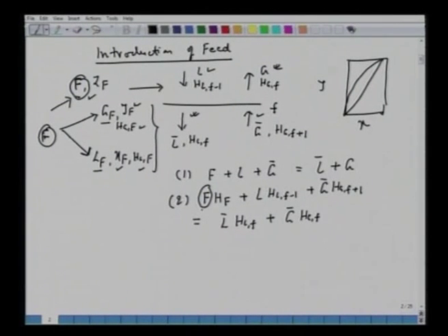Let's just work on this total molar flow rates of the feed as F, and this has a total enthalpy, specific enthalpy as HF, which can also be written in terms of HGF and HLF, etc. Now we make one assumption here that since the temperature drop across two consecutive trays is not very significant, one can assume that a specific enthalpy HLF minus 1, the specific enthalpy of the liquid arriving from plate F minus 1, is same as HLF, the specific enthalpy of stream leaving this plate F here.